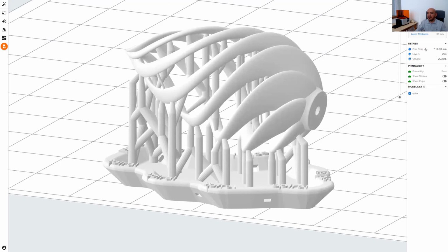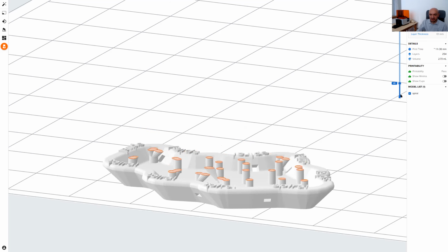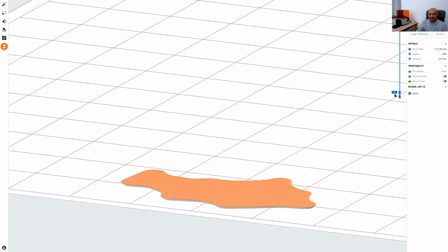Another thing, let's focus on how the part is fabricated. Another nice feature of this SLA printer is that they have a raft here. If you don't have this raft, then at the end of the printing process, it will be quite difficult to remove the part from the build plate. I had these difficulties.